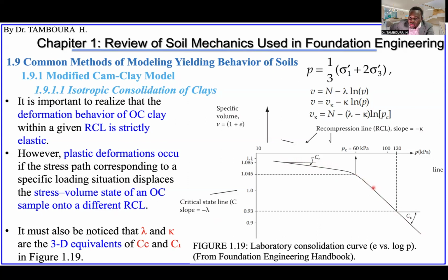They are equivalent: this is in one dimension, and this is when we are in three dimensions. So I think that's all for isotropic consolidation of clay. Isotropic, remember, is the same in three dimensions, with the same stress everywhere. If you understand this, it will be our first step to understanding the modified Cam clay model.